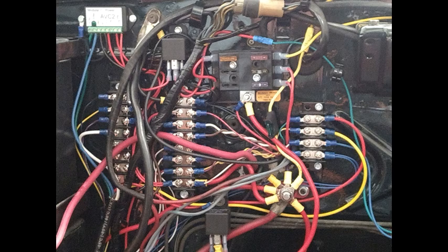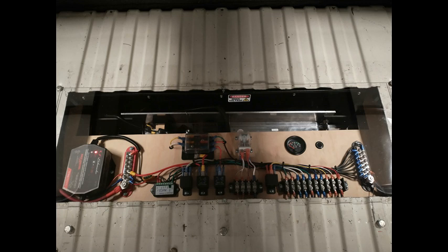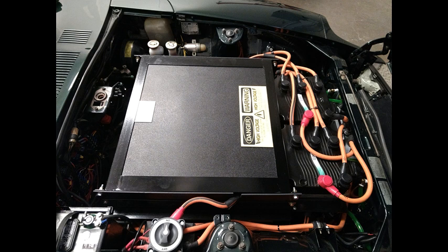Getting back to wire, cable, and conductors, using different insulation colors can help identify and keep track of your wiring. Remember, when routing the wiring, leave a little slack or a bend that will allow for the wire to expand and contract, because whatever you're securing the wire to may have a different coefficient of expansion and contraction, and we don't want the wire getting pulled loose in some manner.